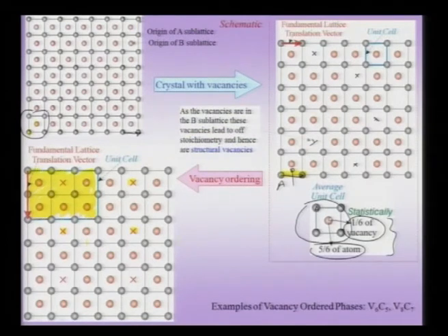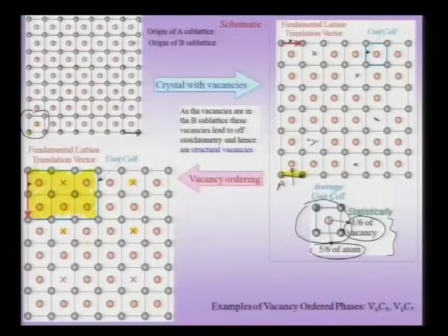So this is perhaps a sort of schematic example of a vacancy ordered phase, and this illustrates the important concept that when defects get ordered, they get incorporated into the crystal structure. In that case the symmetry of the structure changes, and the properties obviously would change along with the structure itself. And in this case, like in case of normal ordering, where we would consider the atomic species instead of vacancies, because of this ordering of vacancies, you can see that the symmetry has been lowered, and my unit cell to describe the structure also changes along with this ordering process.